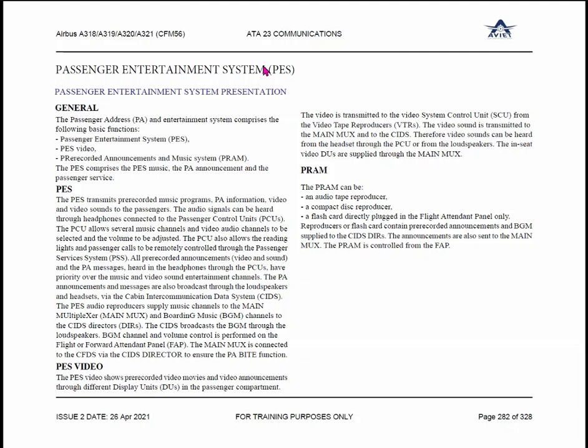Yes, Mr. Dinesh. Just wondering, the strikers for the door, are they energized by the essential bus or the hot bus? It cannot be the hot bus as far as I know. I have no information about it. I need to work it out because it's not my area. It is in the door chapter, so probably they know it better than me. Nevertheless, I believe it will not be the hot bus. Hot bus, you don't have much load, so only the essential airworthiness load you put on the hot bus. It should be the normal bus. Okay.